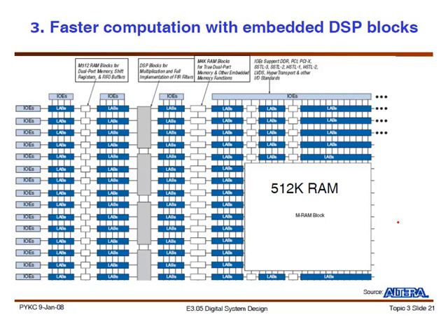This is Altera's mix of memory and DSP and so on, and the text here might not be readable, but essentially what this is, you have basically dual port memory, small memory blocks that you can use, and then this would be the logic elements that you have, the cluster of logic elements that you have.